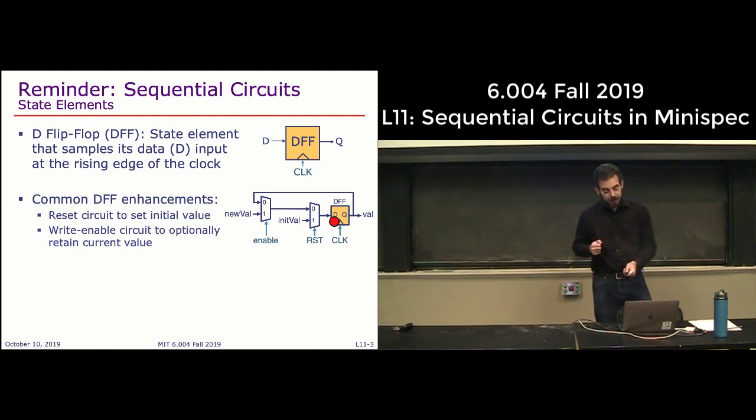And at the input of every flip-flop, we have this mux that basically says, if reset is 1, then just register the initial value that we want to have in the flip-flop. Then, after a few cycles, when the power supply is at the level that we want, and we've stabilized all the values of the flip-flops, then we drive the reset signal from 1 to 0, and we're off to the races, right? Then we can start doing interesting computation with these flip-flops.